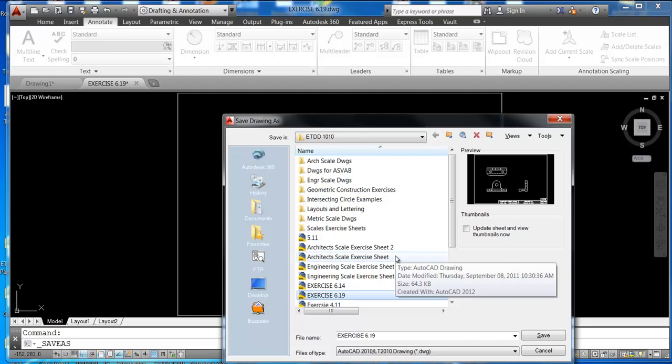That way when you open up your layout for the next drawing, everything's going to be set, including your Dimension Style Manager and your DIMTMOVE setting, which keeps that awkward radius extension from importing itself into your drawing.